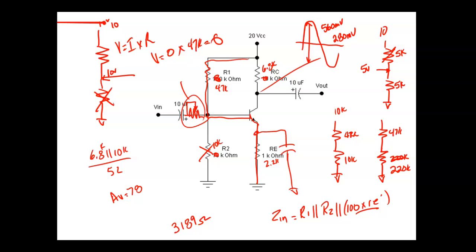So what's the base voltage going to do? It's going to go up a lot, which should cause the transistor to saturate. Do y'all understand why? Yes or no? Normally we ignore the emitter resistor because it's so big. Here I can't ignore the emitter resistor because now it's setting the base voltage.